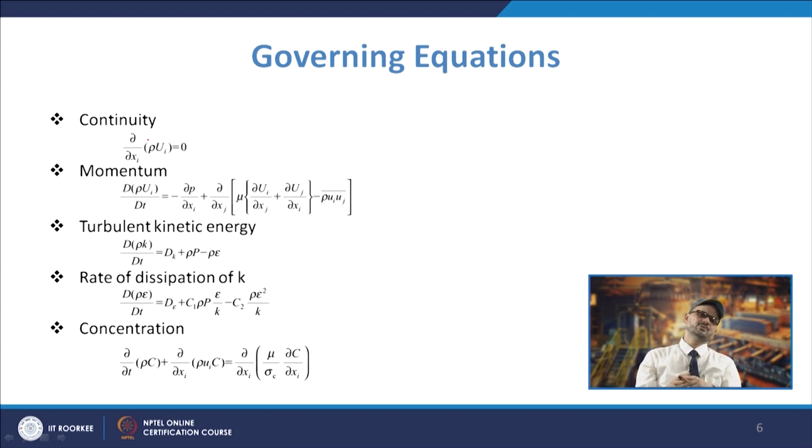What we do in this case is to know how good a Tundish is for mixing, how the flow behavior is, and how the concentration is changing at the outlets when something is coming through the inlet.